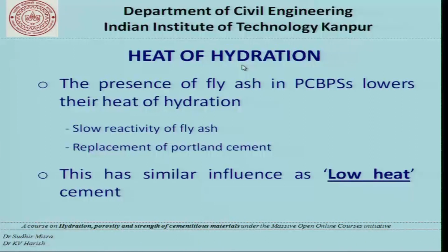Now the next property is heat of hydration. The presence of fly ash in Portland cement based paste systems lowers their heat of hydration. Very important point, and this is one reason why in structures where heat of hydration is a very critical factor, fly ash is used as a very important material in concrete.